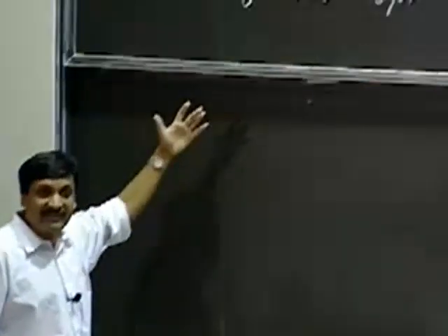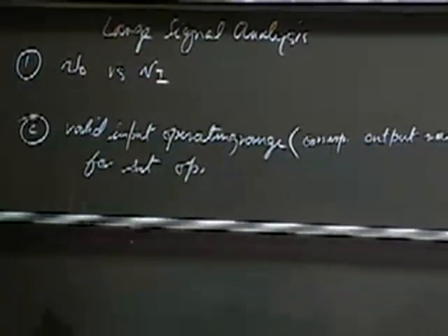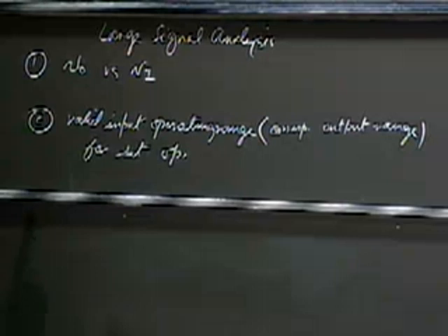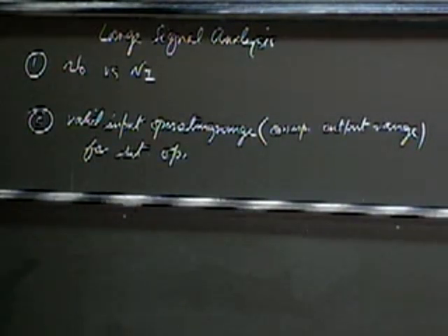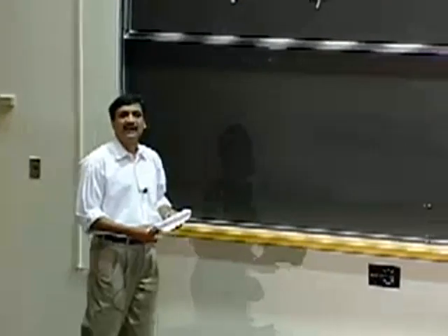So what we're saying here is that if I'm careful with how I apply Vi for a given value of RL and Vs, and for a given choice of my MOS transistor, then I can stay within saturation provided I select my input voltages carefully. And the analysis we will go through today will figure out what that range of input voltages is. Again, I will use the MOSFET amplifier as a motivating example, but in general, large signal analysis would apply to any other circuit as well.